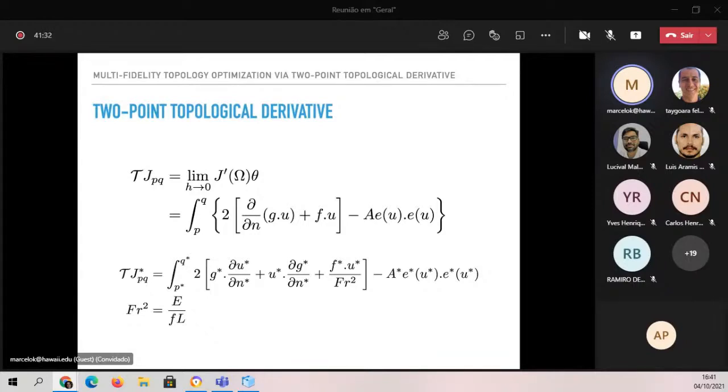What you see here is that the first term within the bracket has a derivative of the normal component of the displacement at the static solution, multiplied by sigma, the stress. It's the traction that you have at the boundary. So there is no variation of u star in the n star direction. Think about that as dw/dz in a thin plate. So that's 0. So that first term inside the bracket is 0.